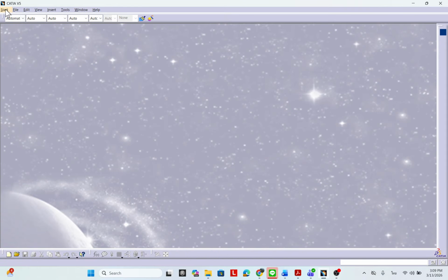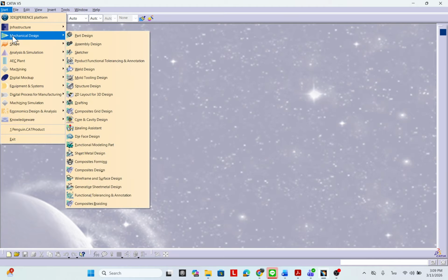Okay, another way, this is way number one. Another way you can use it directly. Focus on the tools of Part Design. Part Design is used when you need to create a solid model of just one part, one component. Assembly takes multiple parts that come into the assembly module and are assembled with each other. Right now, I bring you to Part Design first.